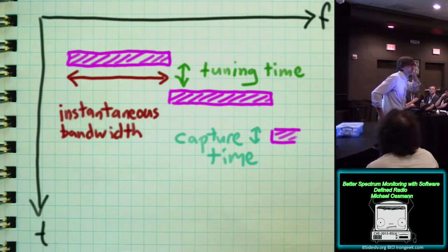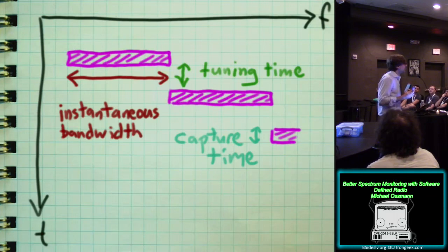Excellent point. You could run into problems with calibration in that case. All of these things have little clocks in them, and you can't really trust any clock ever, right? You know the old saying that a man with two watches is never sure what time it is, but the guy with one knows exactly what time it is. That's the case in all digital electronics. Everything has a clock, and some of them are closer to being right than others. It's really hard to take measurements unless they're all synchronized in some way. And that's one thing that HackRF can give you that Realtek dongles can't: there's a clock input and output, so you can clock synchronize multiple devices.